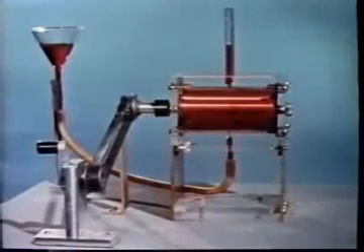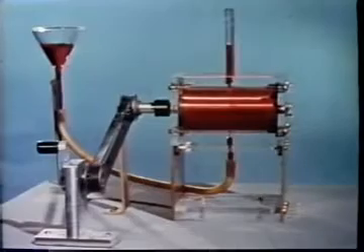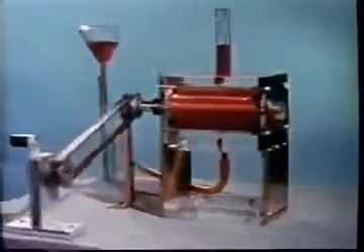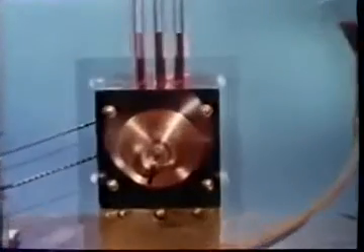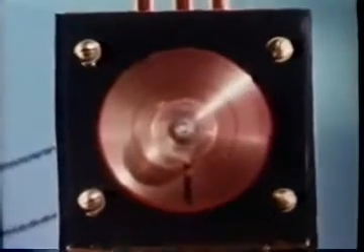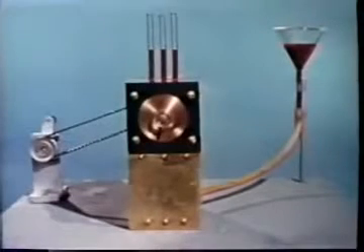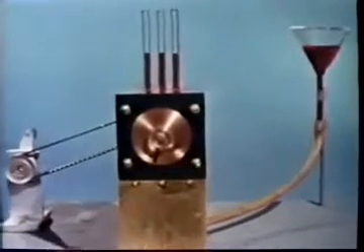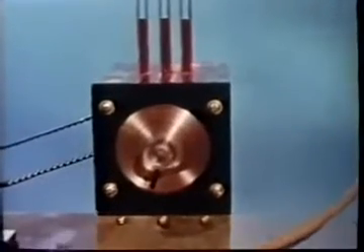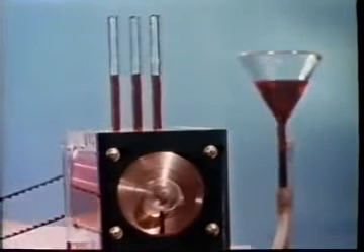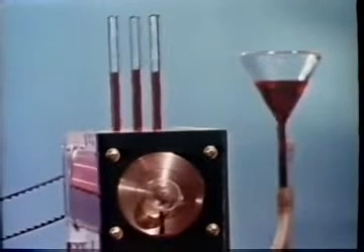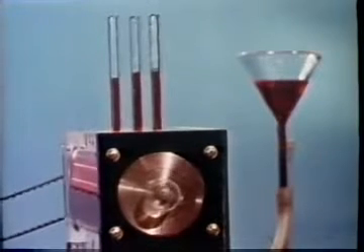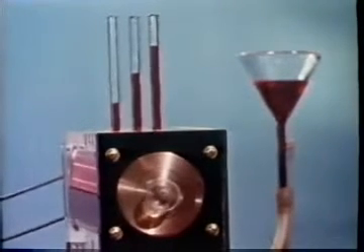This model journal bearing has been fitted with 3 manometers midway between its ends. The shaft is fixed with its narrowest gap at the top. The center manometer is located at the narrowest part, with the other 2 equally distant from it. Here the fluid is water and the manometers are open to the atmosphere. In the converging channel, the pressure rises above atmospheric and then falls below it an equal amount on the diverging side.